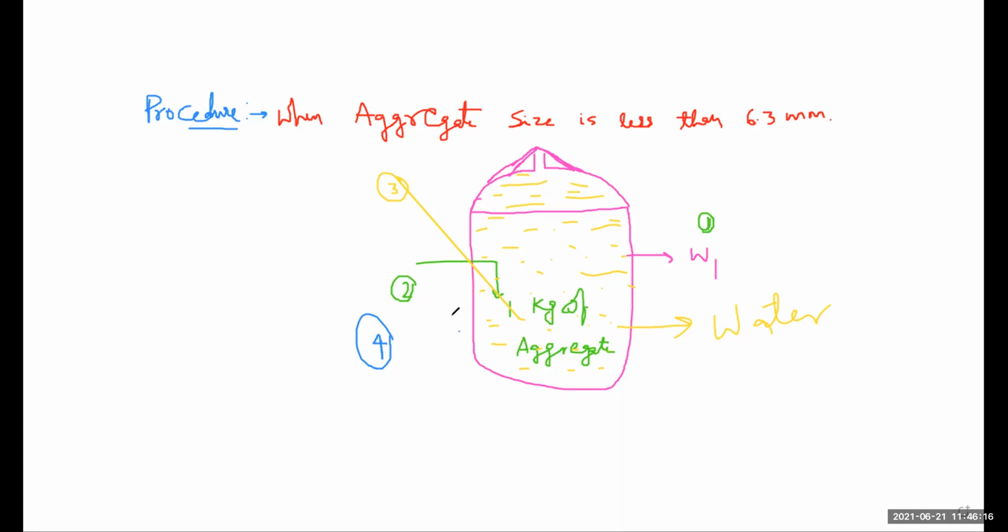About 1000 gram of clean sample is taken into the pycnometer and is weighed. Then water at 27 degrees Celsius is filled in this pycnometer. Here we fill this water. This yellow mark is our water, which will be present in this pycnometer.